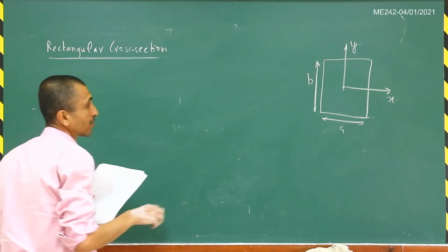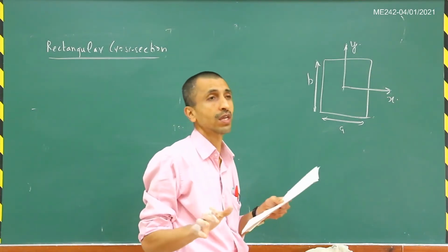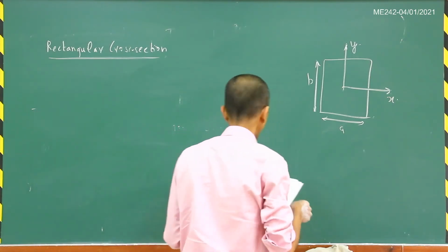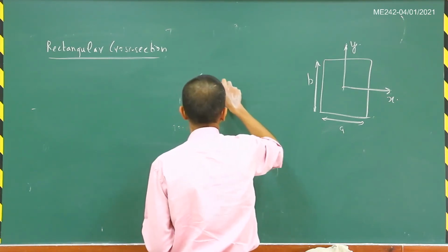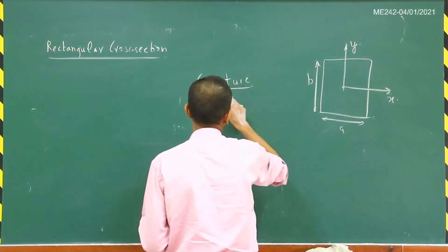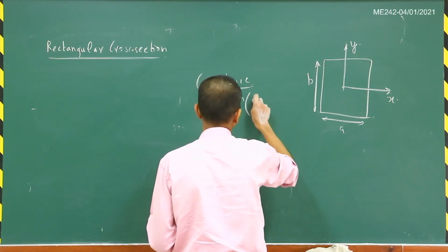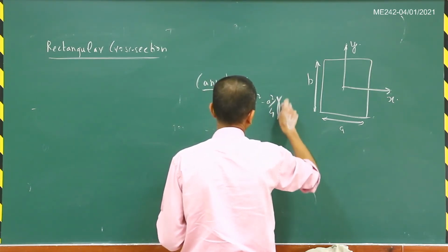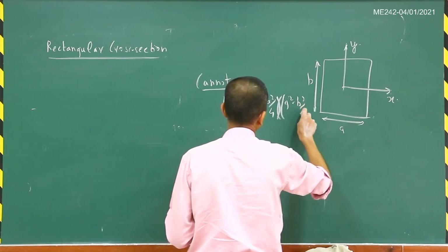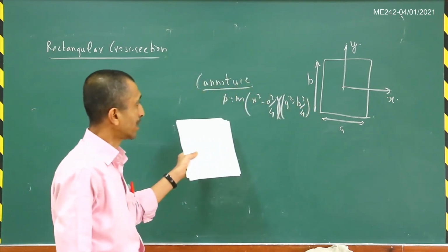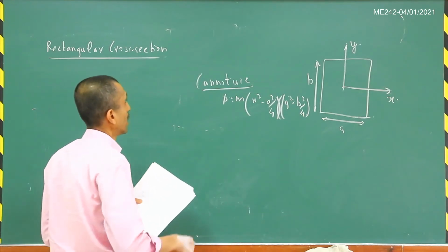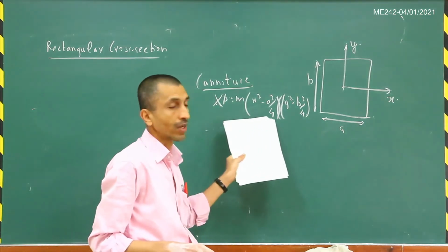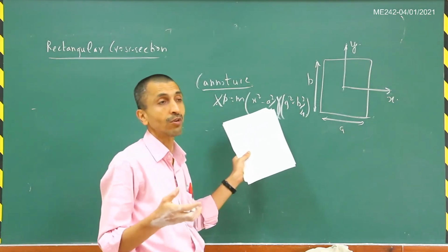So here, this is what I was saying, that you cannot use just the equation of the boundary multiplied by a constant, right? So you cannot use phi equal to m times x square minus a square by 4 times y square minus b square by 4. Just the trick that we use for the elliptical cross section, we cannot do that. This does not work, because you will not get del square phi equal to a constant. We need del square phi to be minus 2G alpha.